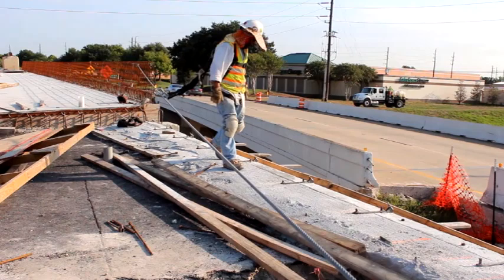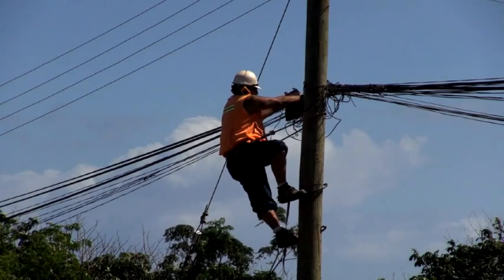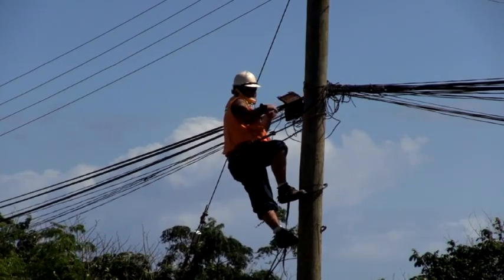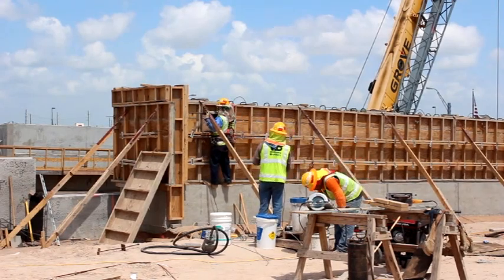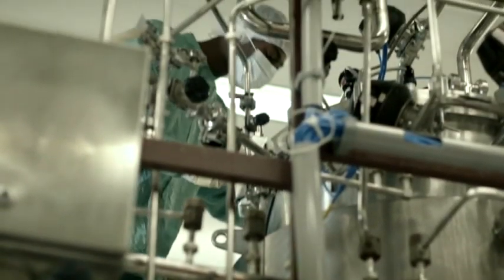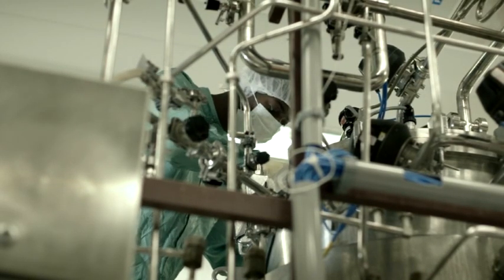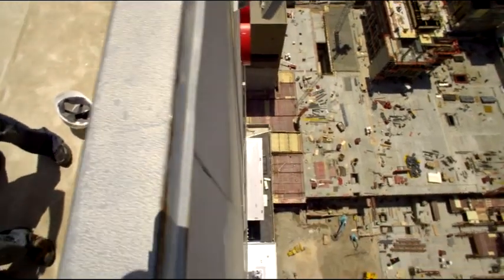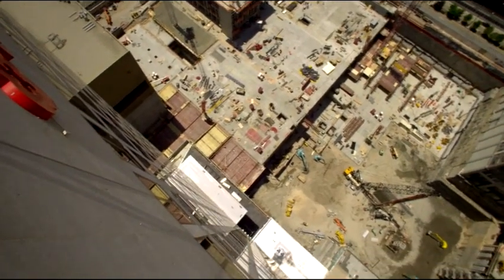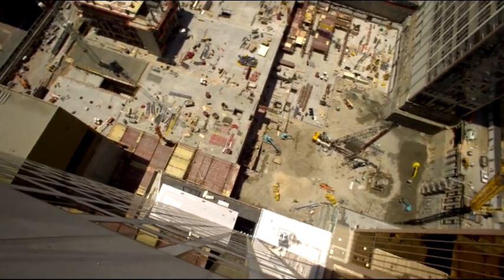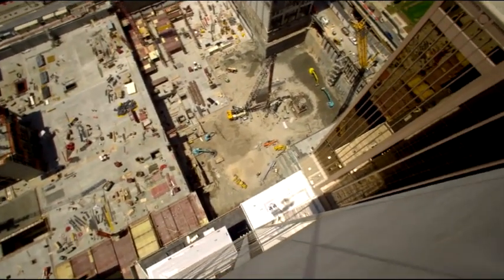In some construction situations, the height requirement for protection can be different. It is important to know which OSHA regulation is applicable to your work environment and to provide fall protection when required. Employers must provide protection for employees who are exposed to the hazards of falling into dangerous equipment, regardless of height. These requirements are based on systems and procedures designed to prevent employees from falling off, onto, or through working levels, and to protect employees from being struck by falling objects.